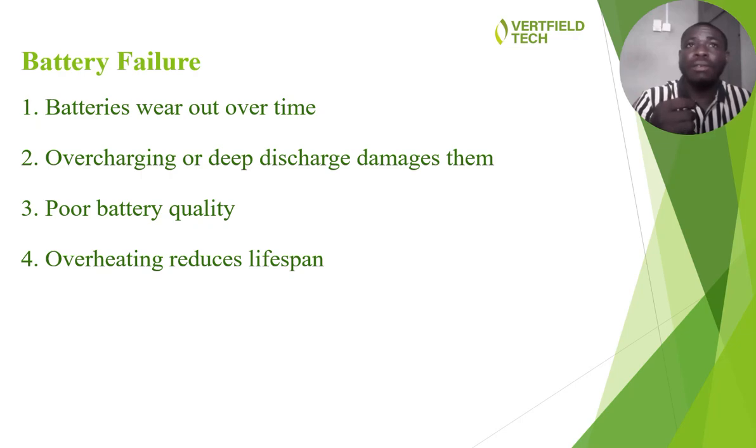And once the battery management system senses over voltage, sorry, not over voltage, overheating or over temperature, it will automatically trigger the battery to turn off, what we call deep sleep. So when your battery system goes into deep sleep, no matter what you do, it will not come up. Even when you supply over voltage to it, it could also lead to your battery system going into deep sleep, which is also called battery failure.